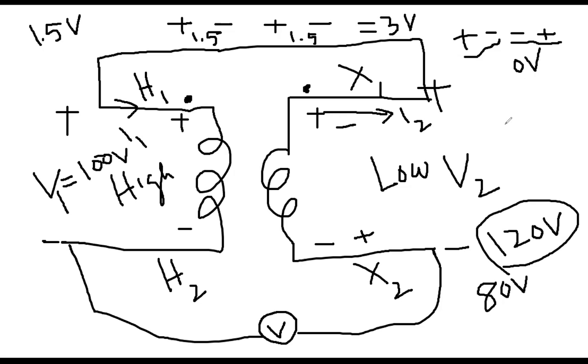So, that's why I mentioned the battery example. Think about the battery. For example, you want to connect three batteries in series. How do you do that? You properly maintain the plus minus sign, right? Plus minus, then another plus minus. Then if it is 1.5 volt batteries, it will give you 4.5 volt, or in this case 2 batteries, 3 volt. But if you connect in the opposite way, then your circuit will not work. Whatever device you are using, it will give you zero voltage. In other words, it is subtractive.